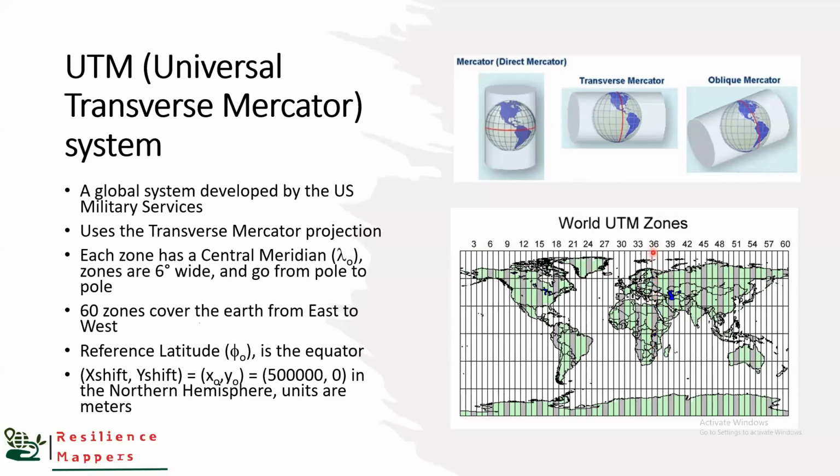You can see here, if you can see the screen very well, we lie in this zone of 36. That's why usually in most of the projection systems that you'll see, it's UTM. You hear that it is WGS84 UTM zone 36 north. Now, when you hear something like that, it's north because Uganda, as you can see, is crossed by the equator. So some part of it is in the upper hemisphere, then another part is on the lower hemisphere.